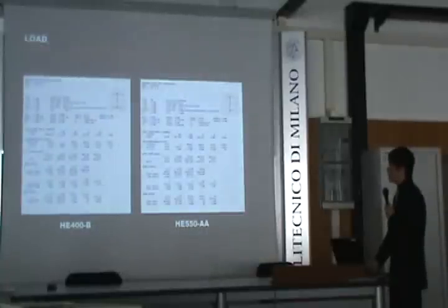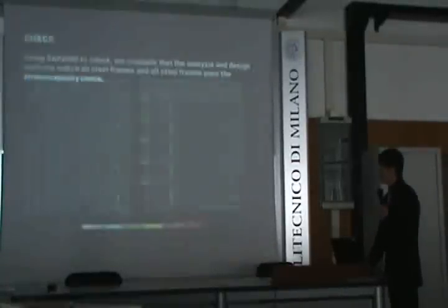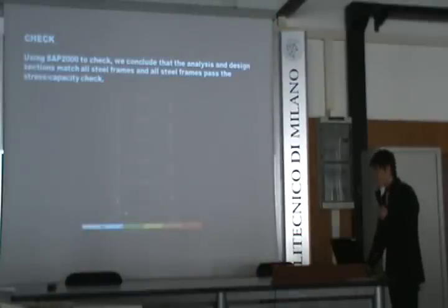Now I need to check the steel profile sections. The status is okay. And finally, I will check all frames. Using SAP2000, we can conclude that the analysis and design sections match all the steel frames, and all the steel frames pass the capacity check.